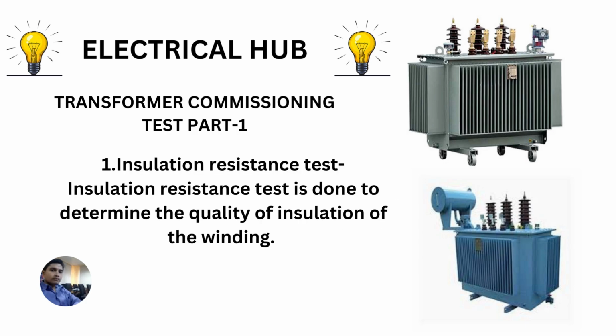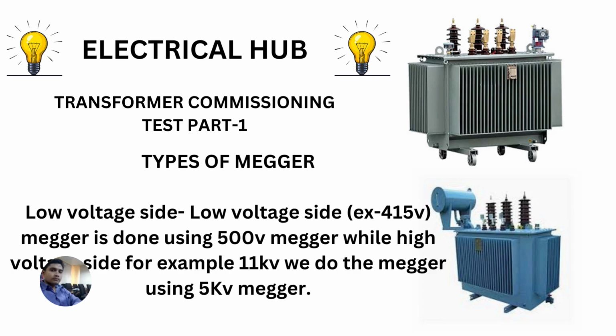Let us start with the tests to be conducted before charging the transformer. First is the insulation resistance test. The insulation resistance test is done to determine the quality of the insulation of the winding. For a transformer, there is a low voltage side and a high voltage side. The meter we are going to use depends upon the voltage.